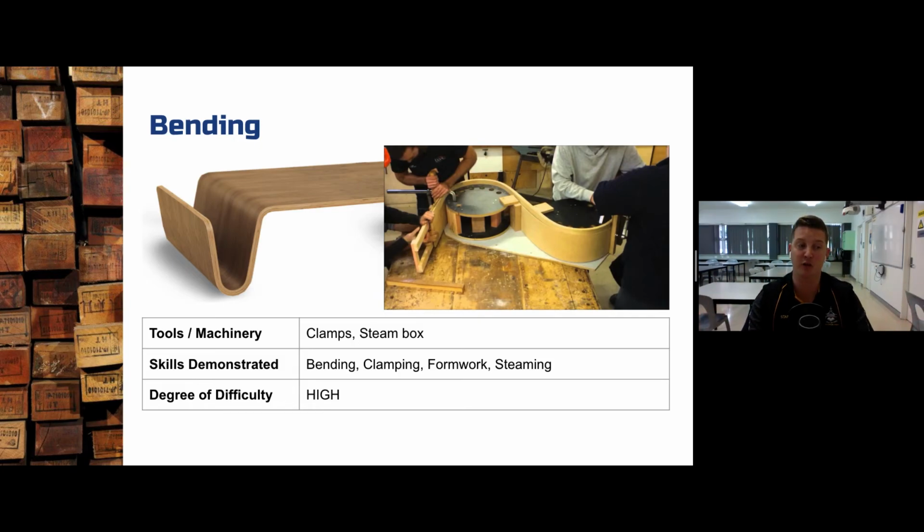And that's why if you have a tree that's got a dead branch on it and you pull it, it simply just snaps off. This is how bending works. If you want timber that is dry to suddenly become flexible again, you need to introduce the moisture back into the timber. And we do this usually by soaking it in water, boiling it in water, or putting it in a really moist environment such as a steam box, where we're artificially adding moisture into the air so that the timber can absorb it. As soon as the timber becomes green again, it becomes a lot more flexible, a lot more pliable, and therefore easier to bend without it breaking, without the fibres snapping off.